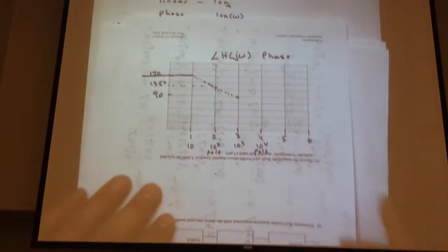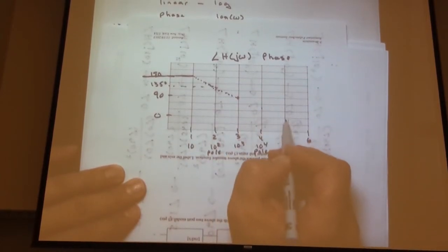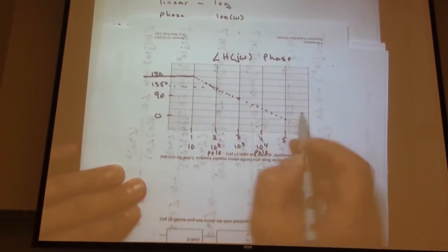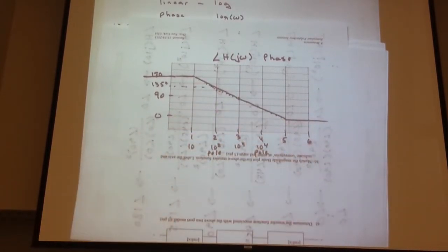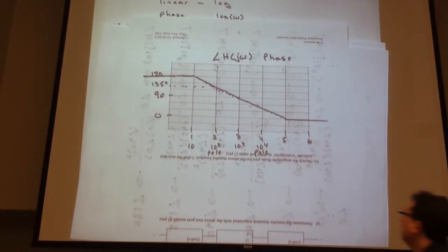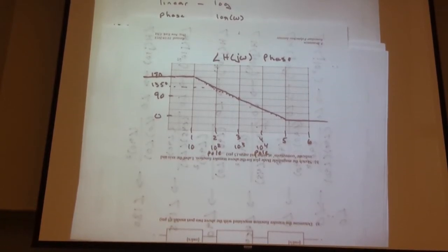And so if I turn this back over, there's 0, there's 45, and there's a phase plot, Bode phase plot. Something to note here. In the magnitude plot, crossing a pole or 0 changes the slope. In the phase plot, crossing a pole or 0 is an absolute change. So there's our rules for phase Bode plots.